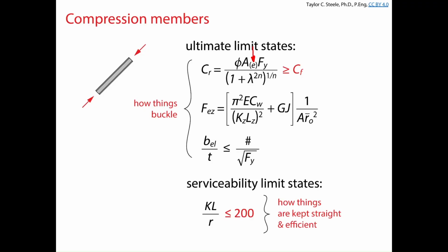Last day, you also saw, in addition to the elastic buckling from Euler's elastic buckling load for weak or potentially strong axis, there is also potentially the ability for certain sections to buckle torsionally. Basically what you have to do is calculate the FE values for the weak axis, the strong axis, and the Z axis, which is twisting. Depending on which value of FE is the smallest, you use this FE value to calculate lambda and use that value of lambda to calculate CR.